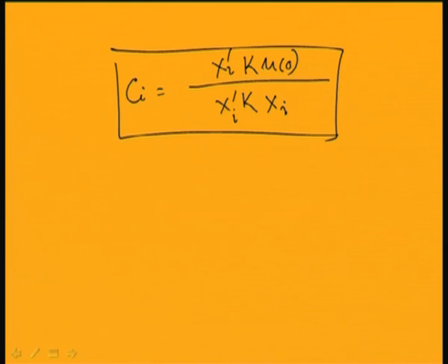So, from the known stiffness matrix and mass matrix I can find the modal participation of different modes in the resulting free vibration of a system.